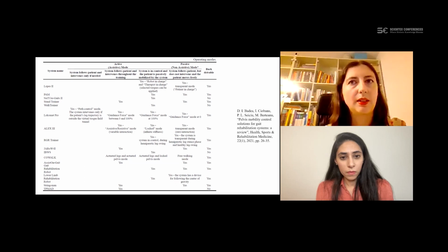Perfect back drivability is when the torque is 0 with no friction or stiffness involved, which is difficult to achieve, if not impossible. This is why systems that provide high mechanical transparency have highly back drivable actuators, meaning that the mechanical transmission friction and the torques are as close to 0 as possible. This allows the robot to follow the user, who moves freely, unconstrained.